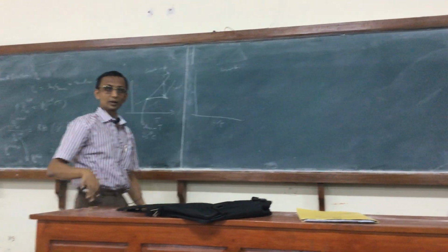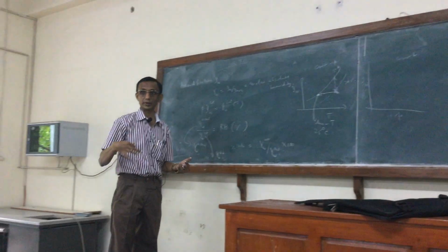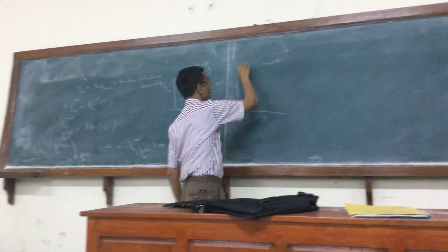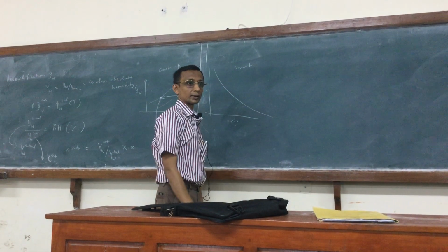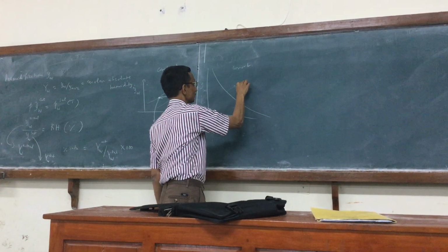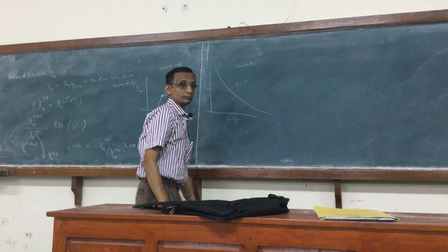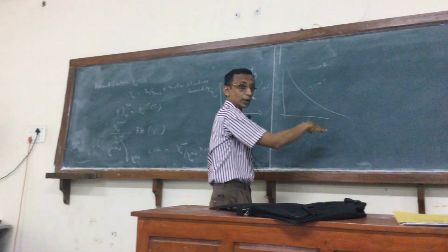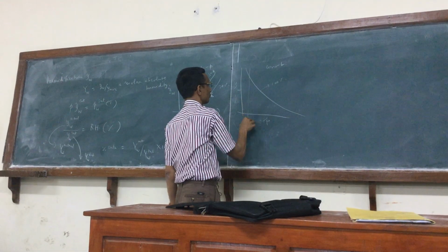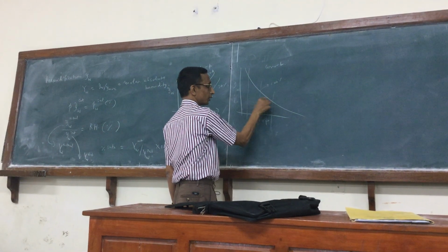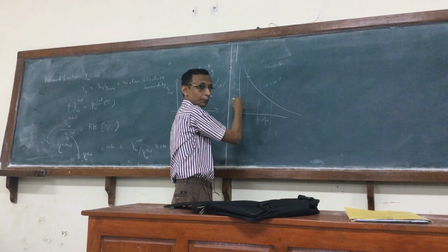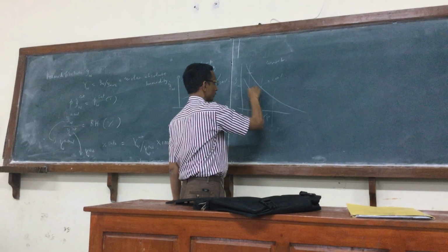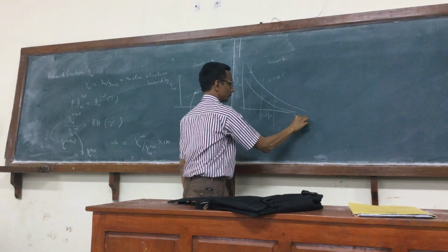You should know how to plot this. We've seen how these diagrams look. It is inversely proportional, almost like a hyperbola. So you get a curve like this. Let's say this is 100% saturation. Now 80% relative humidity will look like this. It will be below again. You just have to mark off at each temperature this distance; if I take 0.8, I get the 80% relative humidity curve.